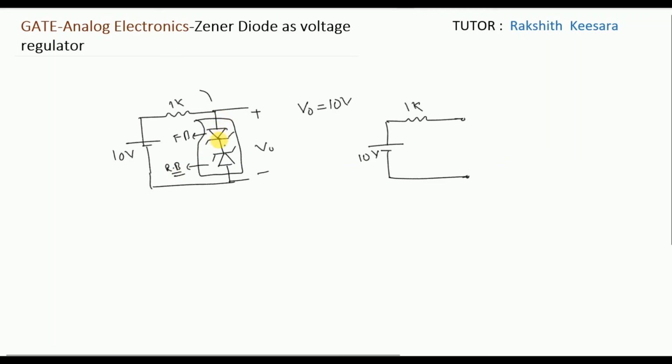So for forward bias, what is the equivalent circuit, guys? We should draw voltage in opposite direction. And he mentioned V gamma is 0.7 volt, and Vz is 5 volt. Next, this Zener to be in reverse bias. So what is the equivalent circuit, guys? So this is the equivalent circuit. This is 0.7 volt. This is 5 volt. So total voltage is 5.7 volt here.